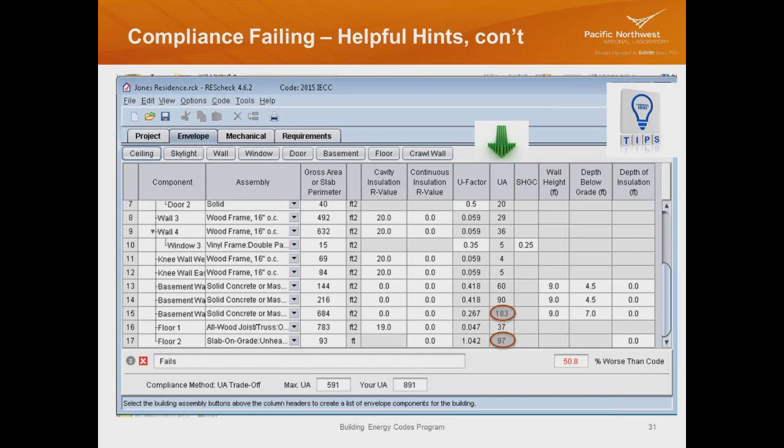If you had the entire slab insulated, that would typically only happen if you had a hydronic heating system within the slab. And when I say heated slab, I'm referring to a hydronic heated slab, meaning the actual slab is heated, not that the house is heated. That is a question that has come up, so keep that in mind. There are 2 options in the software: heated and non-heated slab.